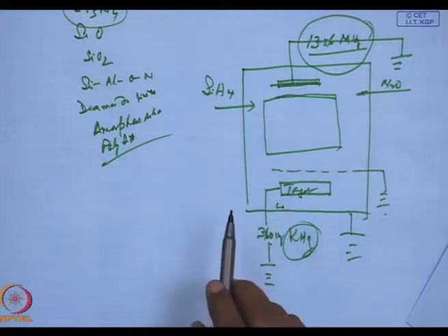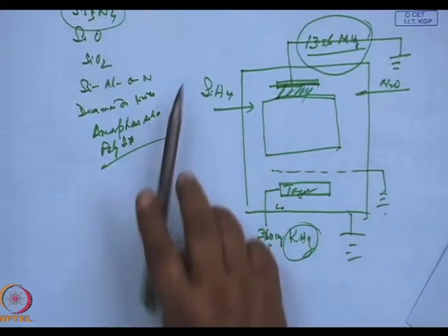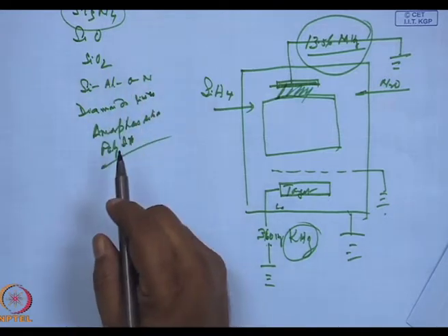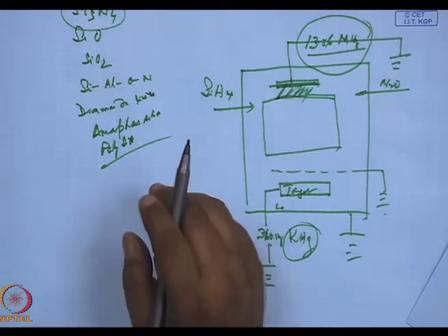In such a case, I will have a silicon nitride plasma on the substrate at room temperature itself, and a very hard adherent coating of silicon nitride.